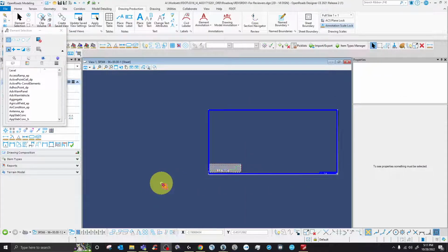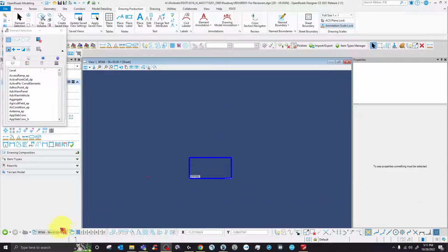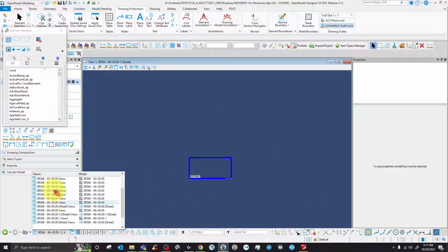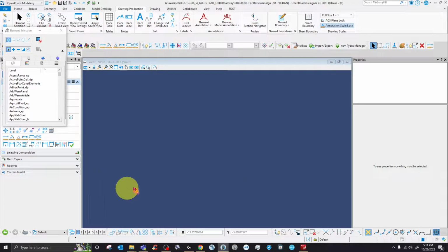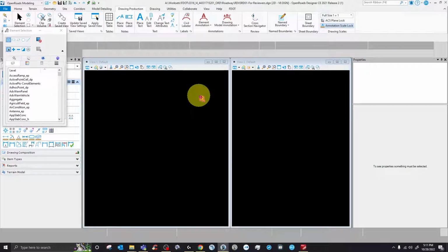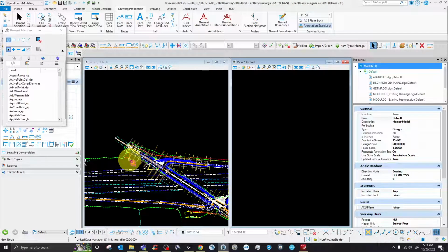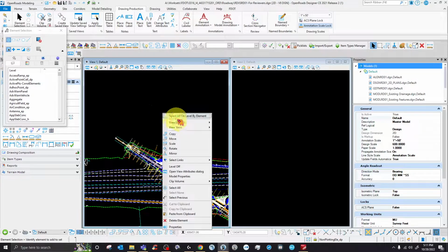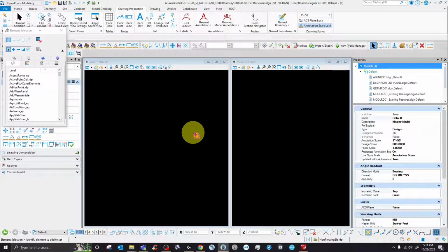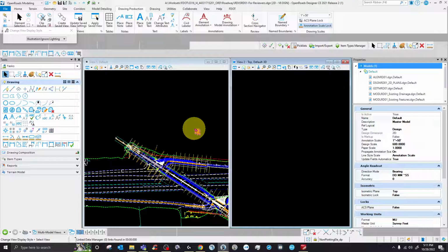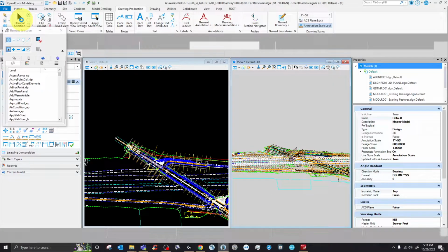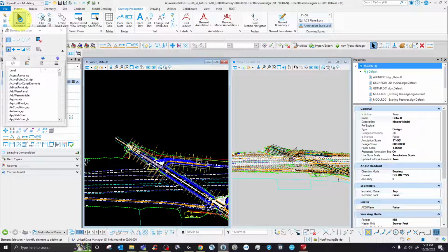Okay, we are back. I actually forgot one important thing, because when I did that Bentley training, I remembered what they said. Do not cut sheets at the beginning. Just cut the cross sections first and then do the sheets later. Which is a big mistake that I made at the beginning of this video, because I was in a hurry and I should not have done that. So, okay, let me show you what I mean.